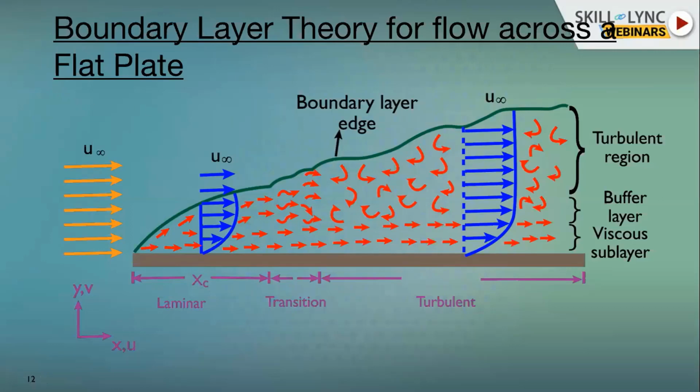So now the broad picture we can divide into several zones. First, the zone where the fluid motion is affected by the presence of the solid layer, right? That zone we call the boundary layer zone. Then there is a zone where the fluid has a uniform velocity as it is. We call it the core or the outer layer.